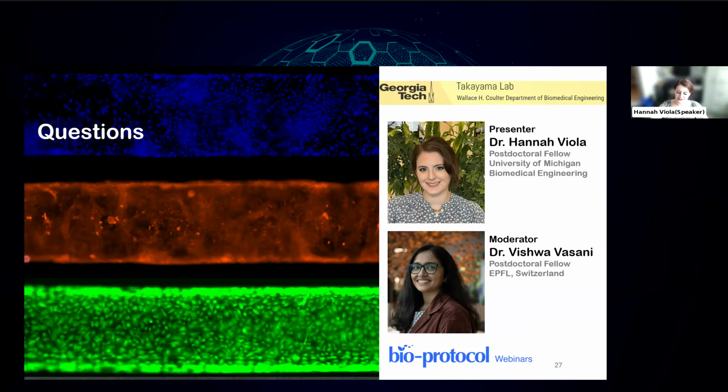The main limitation is the size of tools that you can buy. And I think that's probably also to do with what's physically possible with metal. I don't know how they make these tools, but I don't think you get much smaller than like 1 micron, right? 5, I think, is the smallest I've seen. I've seen people do 1 micron features. I don't know that there's a tool that small, but you can still mill outside of the features and get 1 micron. So it depends on your design. 5 microns is still really small though.